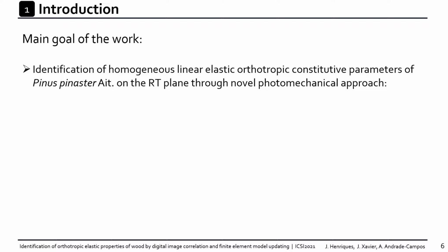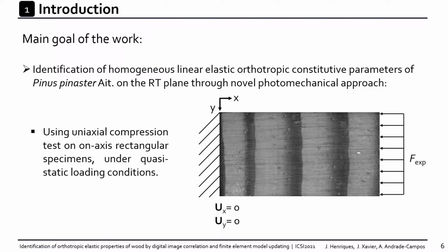This work addresses the identification of linear elastic orthotropic constitutive parameters of Pinus pinaster wood through digital image correlation and the finite element model updating, using a single uniaxial compression test under quasi-static loading conditions with on-axis rectangular specimens oriented on the radial-tangential plane.